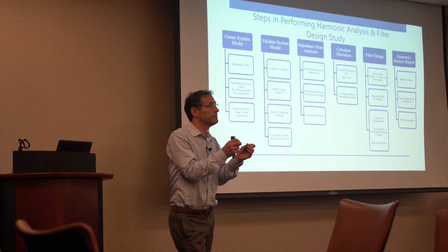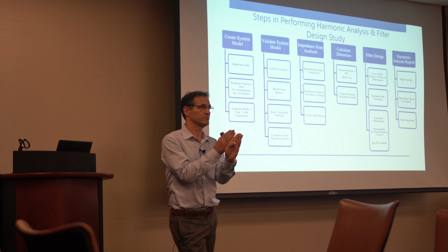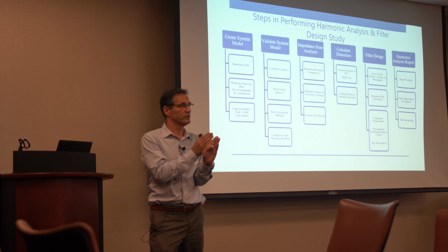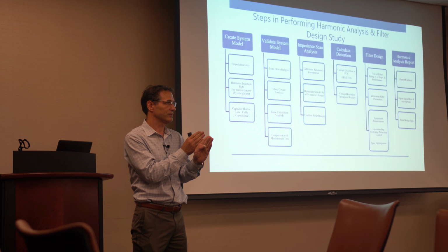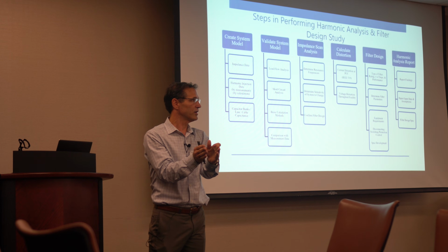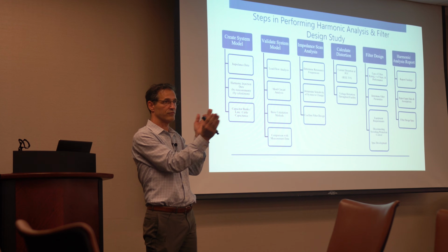When I'm adding those up, assuming that the phase angles are always the same. This is a key concept here. The reality in the real world is those phase angles are not lined up at all. A fifth harmonic from one VFD drive will not line up with the fifth harmonic from another VFD drive. They're phase shifted from each other.